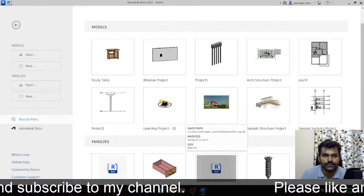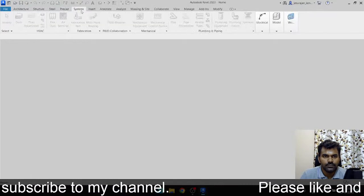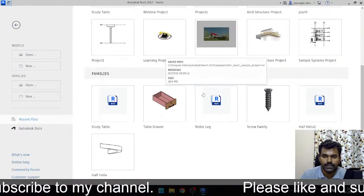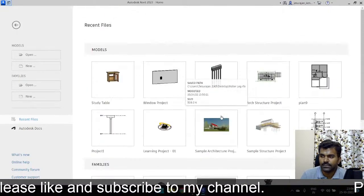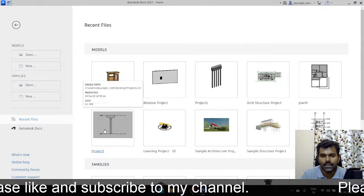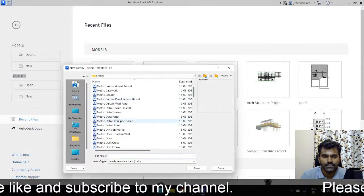Okay, I understood. So this is our home page. If I go back, then I see a gray color window. Don't be afraid. You just have to click this home button, and you can see all these relevant families and all these recent files here. Okay, so this is my way of doing it. In case you want to do it differently, then you can try differently. So I'm going to families, taking new. Let's take a generic model.